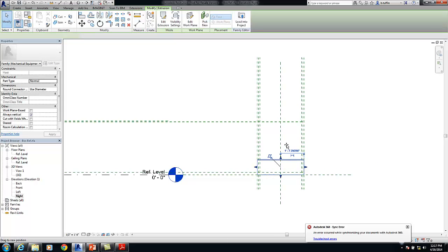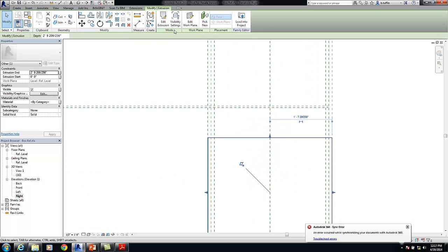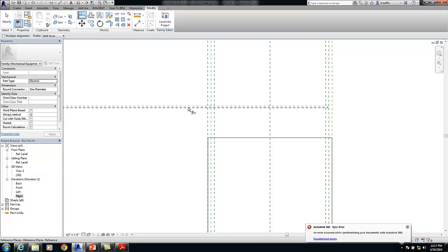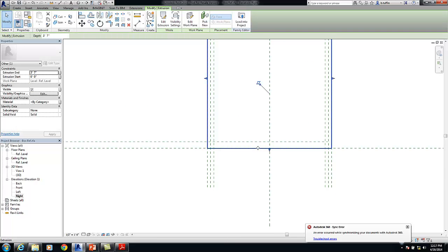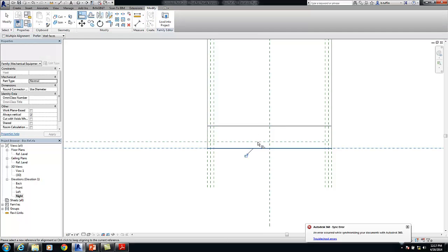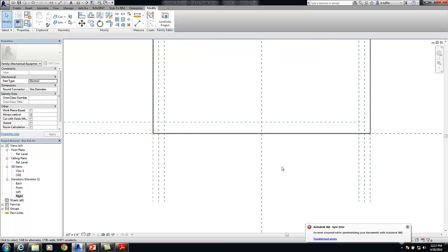Elevation here. And I'm still not done. I've still got to lock this a little bit more. Align it, locking it. Now don't forget about the bottom. On the bottom aspect here, you're really just sketching on that plane. You really haven't locked anything to that plane. So always unlock it or move it to see if it is locked or not. And then go ahead and run an align with a lock to it to go ahead and help out.